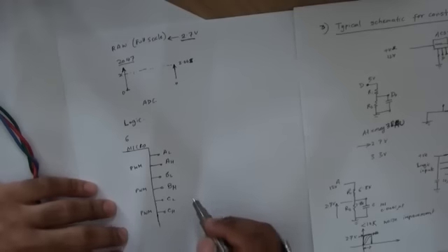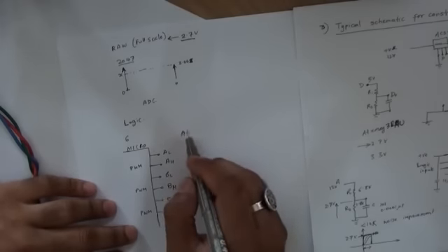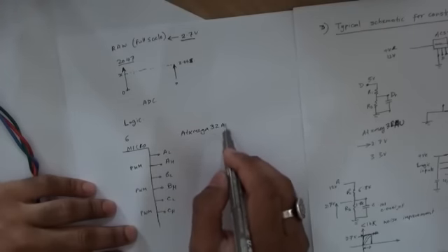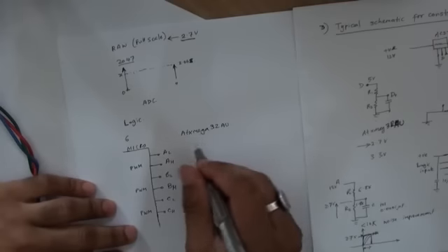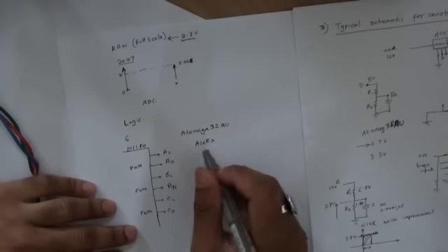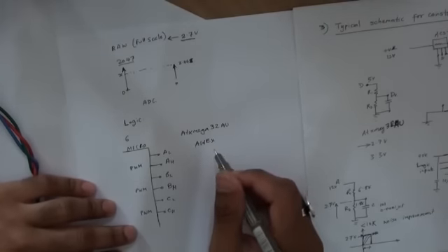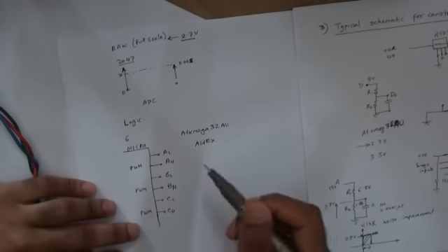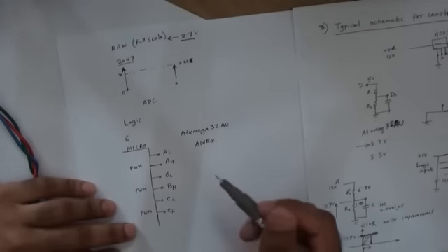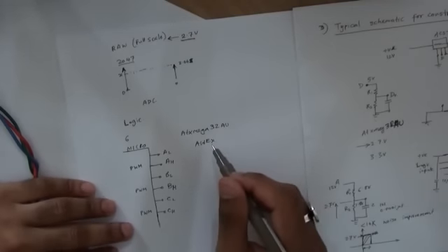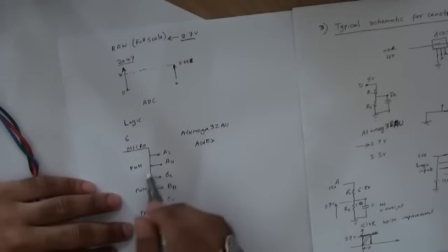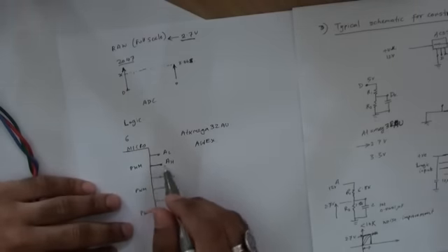Now I have used an Xmega 32 AU. Now this has an interesting feature called AWEX, Advanced Waveform Extension module, which is essentially designed to drive 3-phase or even 4-phase motors like this. If you use that, then you can use the built-in PWM generator as well, so you can pipe the PWM waveform through the high side.